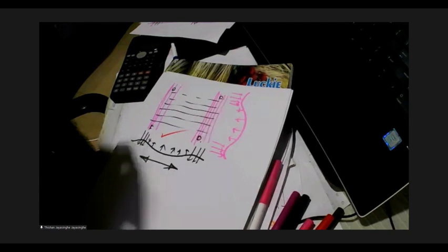We convert the slab to a one-way system, dump all the load onto a beam or a column strip, and then put a concentration of tendons in the beam strip so that we can transfer the whole load onto the column strips.